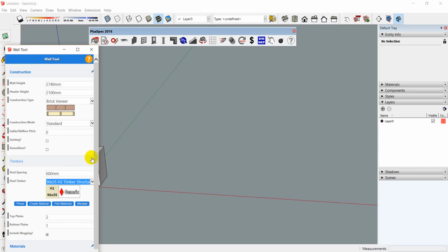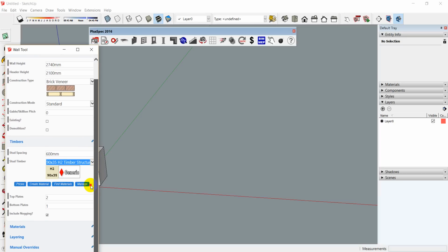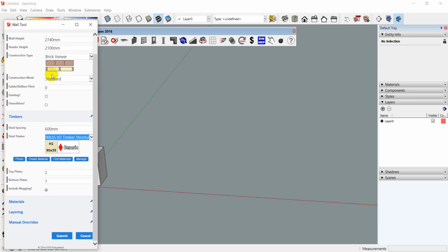So I'm just going to use standard timber framing in my local area, yet you can quickly go back up to this tool up here and change your location to what timbers would be available there. By default 600 millimeters or 2 feet is a standard framing size for the majority of construction, so we've set it as a default, and you don't have to set this. This is how it will come out when you draw.